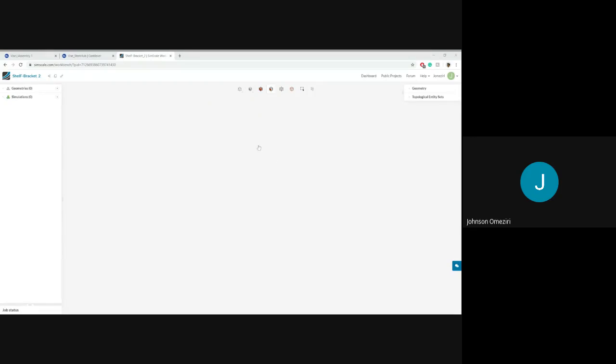Once I click import from Onshape, this window appears. In this window, I click Vice Stem Hub, the one I shared earlier. Then it brings the list of all the objects we created there. So I click on cantilever, then I click on part 1. Then I just click import and wait for it. Once it's done importing, this will go away.